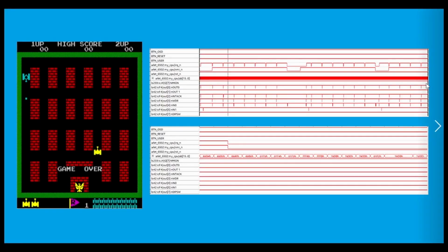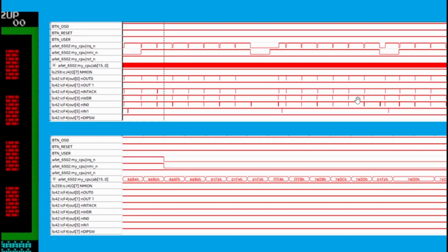During the proper attract mode, we get a glimpse of how the game will operate. We see the NMI pin triggering for the first time during the VBlank period. The lower diagram shows how the CPU cycle happens with the non-maskable interrupt triggered. It's similar to the IRQ, but we have a different reset vector of FFFA and FFFB. The address it goes to for our game is 79DB.